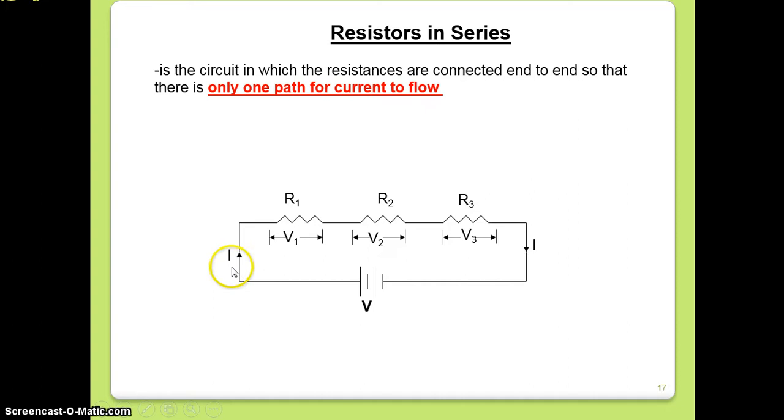So you need to focus here that the voltage provides the current, and the same current flows through the three resistors in this example, and the same current flows back to the power supply, completing the network. You can see here, this current flow gives rise to voltage drop across the element. We represent it here as V1, V2, V3. These are the voltages across the three different elements.